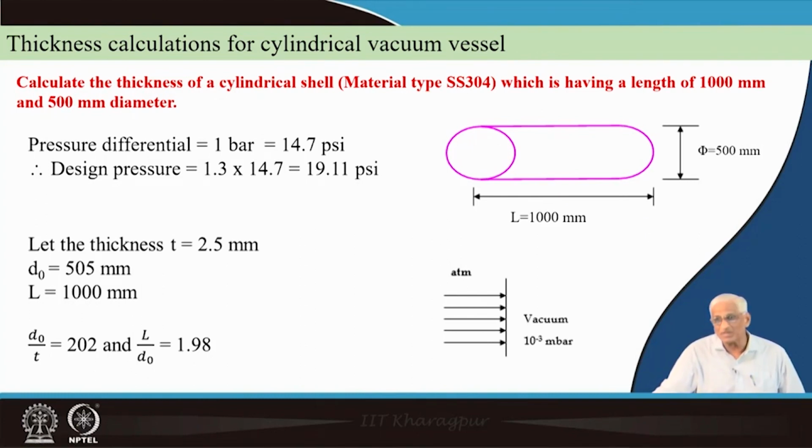Reliability is very important because the pumps and other components are very costly. So, the material with which you are making the chamber also should be quite costly, without any micro cracks. Very good finishing has to be done, sufficient thickness, and if necessary external stiffeners have to be added, all that goes into that. Very detailed design has to be done for ultra high vacuum chambers.